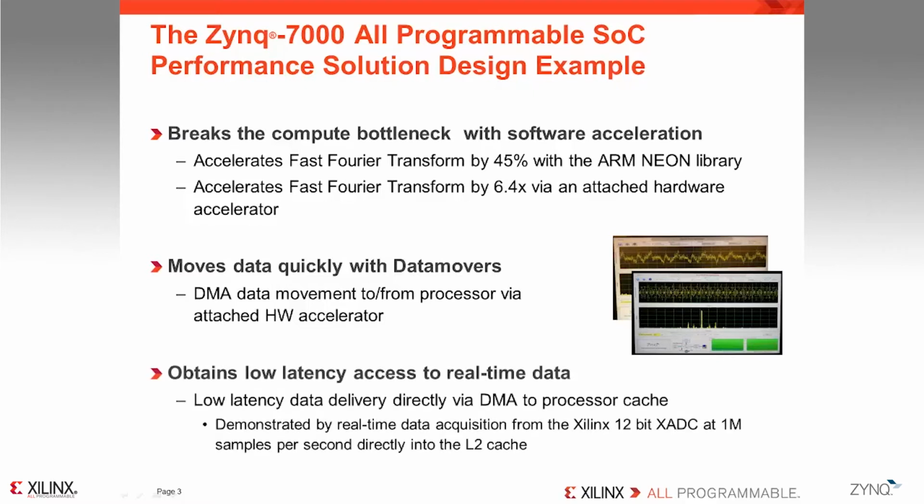Finally, for real-time applications, it is important to obtain low-latency access to real-time data. We demonstrate how one can acquire 12-bit analog-to-digital data via the integrated XADC at 1 megasample per second and pass this data directly to the processor cache via a data mover.